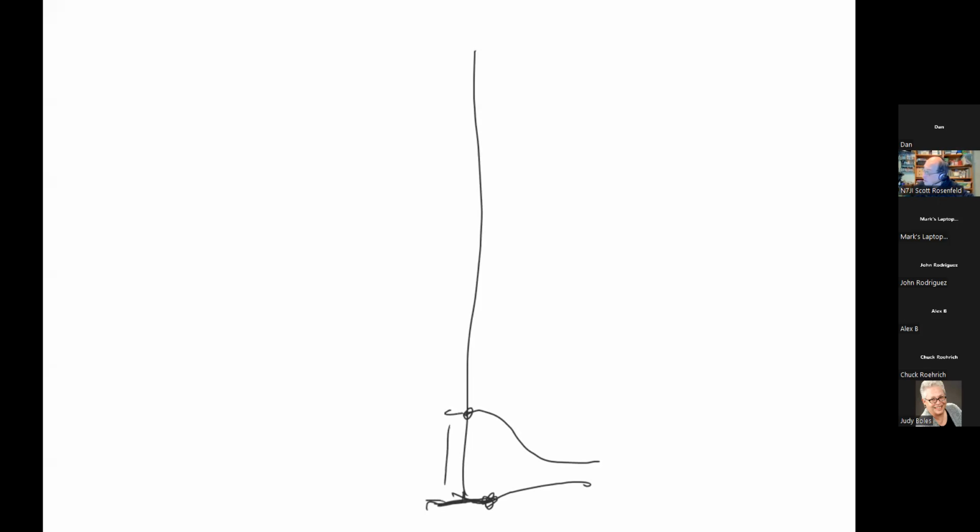By the time you start looking at the distances, you're far enough away from ground that you can actually create a voltage there. This is known as a shunt fed tower. It's a different mechanism for feeding energy into an antenna, even if it's a grounded antenna.